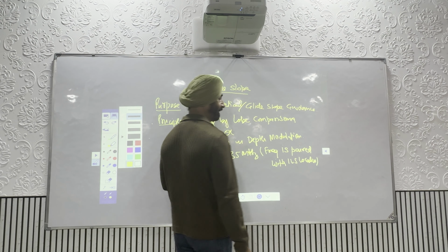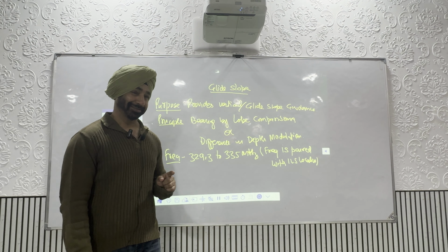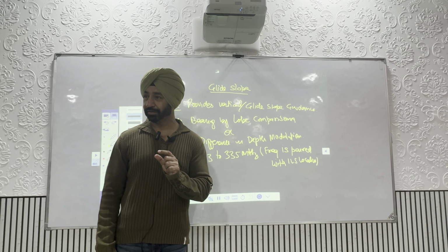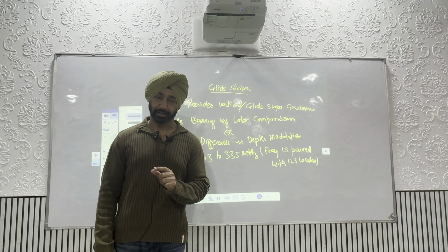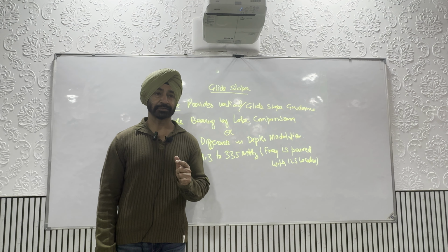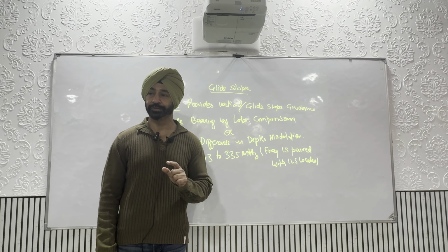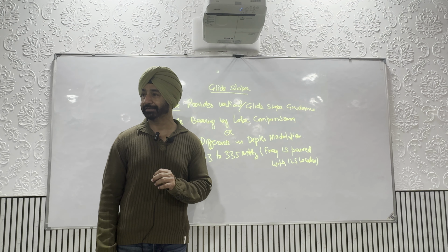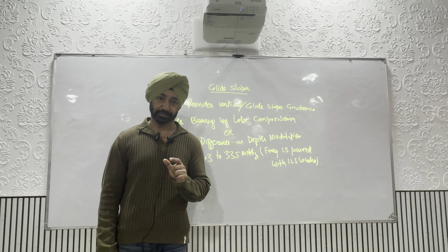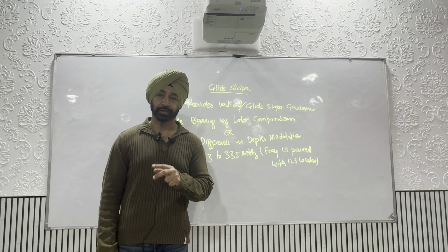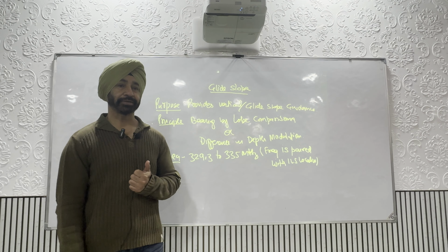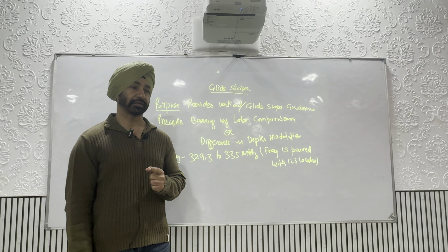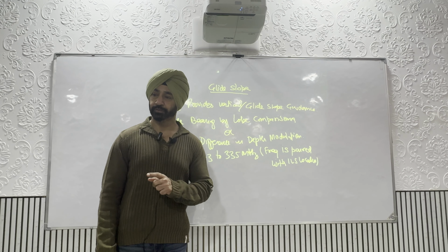Now what is the pairing? Earlier we saw sharing. Sharing was, some frequencies are for VOR and some frequencies are for ILS. Now pairing means if you select one frequency, the other is automatically selected. Whatever it is, for this 110.3, the corresponding glide slope frequency will be fixed. Once a frequency is selected, the corresponding frequency is automatically tuned.